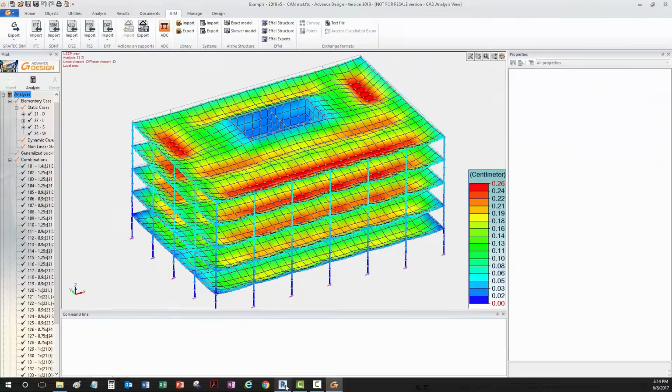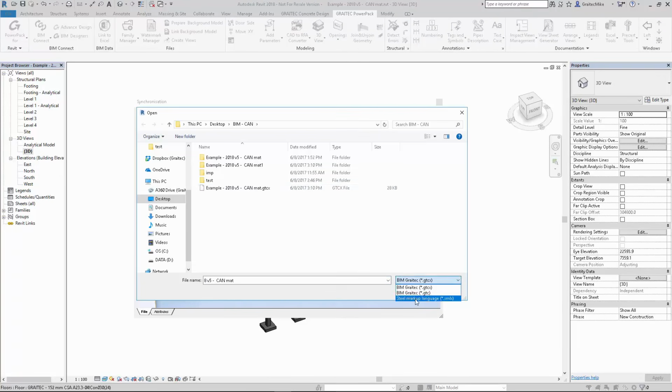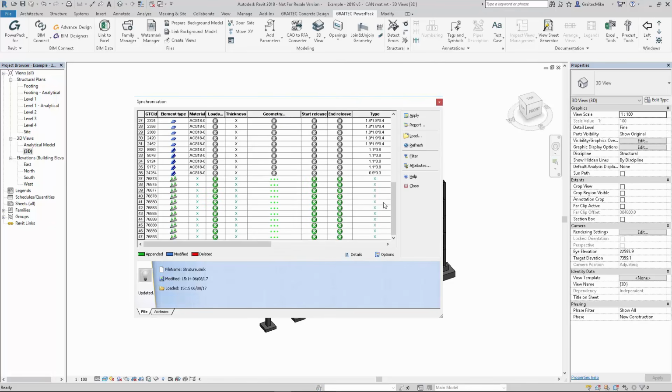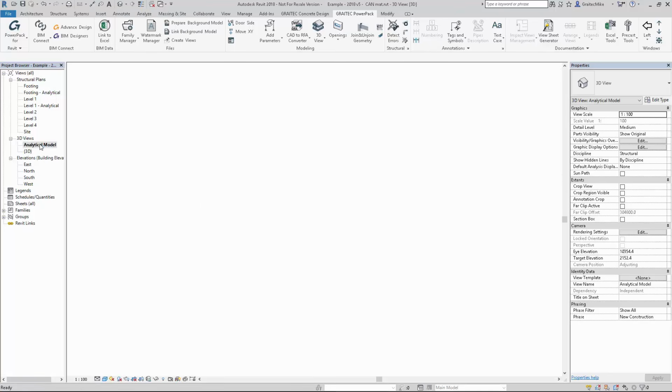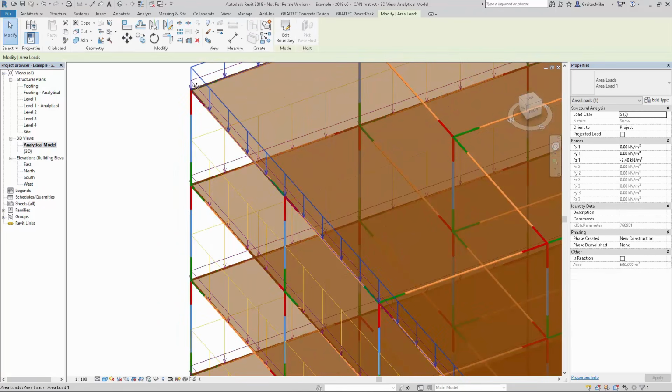This is when we go back into Revit to synchronize that model. Now the synchronizing of the elements is not going to just be the elements that have changed structurally. We're going to synchronize such things as forces, as internal forces, as load combinations, and we could see those green elements in the base of our spreadsheet are depicting forces that had been added. If there would have been things deleted, we would have also been aware and seen that graphically on our screen. We had mentioned that internal forces will also be exported, and we could see the forces that had been imported on our analytical model.